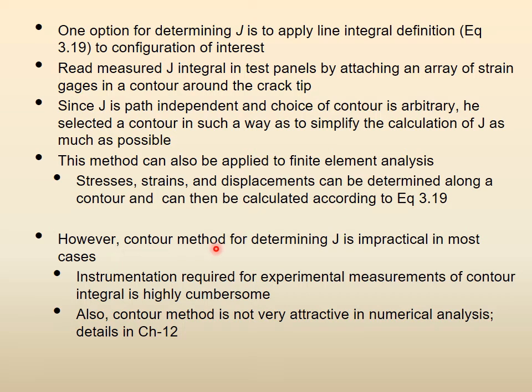However, this contour method for determining J is not practical in most cases. The instrumentation required for experimental measurements of the contour integral is highly cumbersome. You see, you define any curve, and on that curve you place a lot of strain gauges which are perfectly aligned and so on.